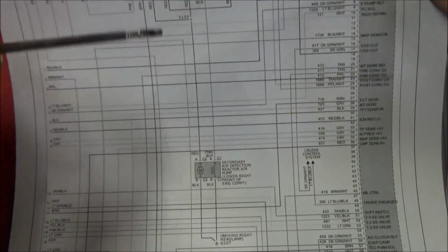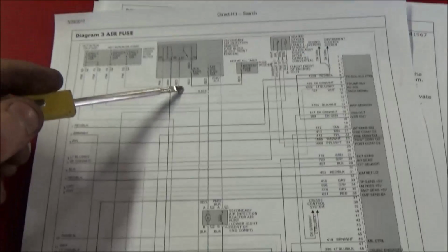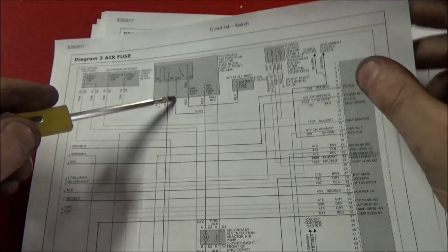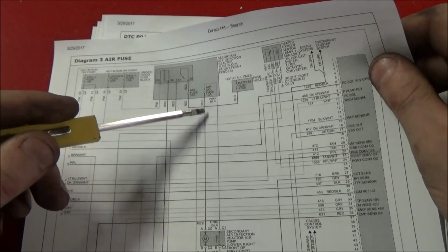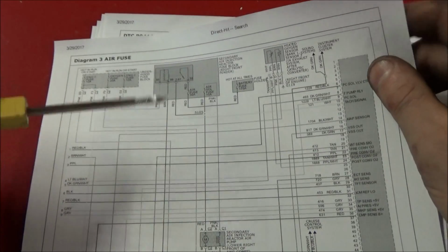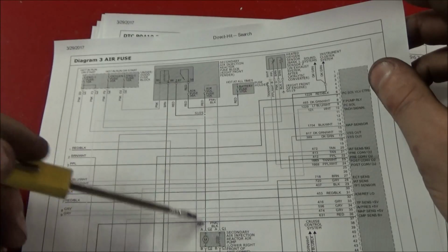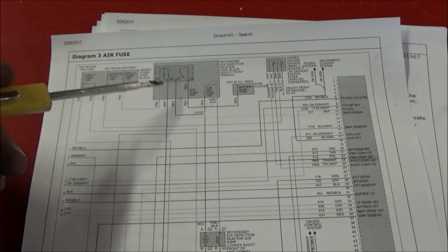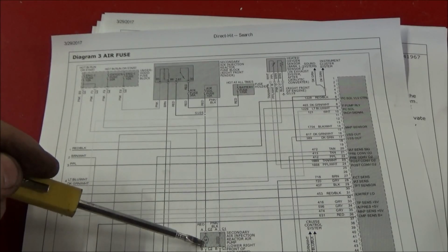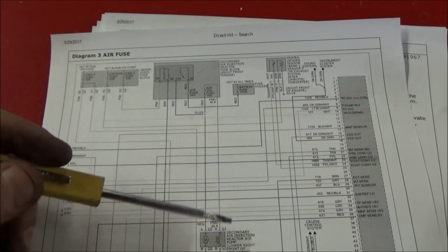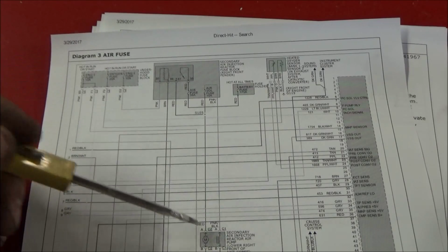And that's really going to tell us that there's absolutely nothing wrong with this relay, at least on the output side. You know, we could still very easily have some sort of issue from this splice onward as far as circuit integrity to this pump motor. But as far as the relay itself, if we can get this solenoid to run, that pretty much confirms that this relay itself is good if we can energize the solenoid with that functional test.